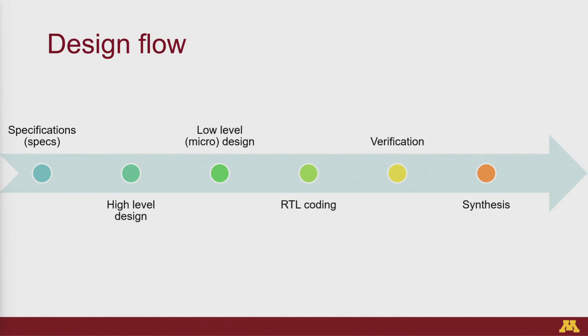Once you code your RTL, we need to first verify that your design actually works, because there's no point in sending out the design if it's not going to work. What's the point of an adder if it does not add two numbers, right? Or in a worst case scenario, if it adds and gives you a wrong result, have you checked all of the corner conditions? For example, does the adder overflow? Does the subtractor underflow? So things like that are what you should handle in verification.